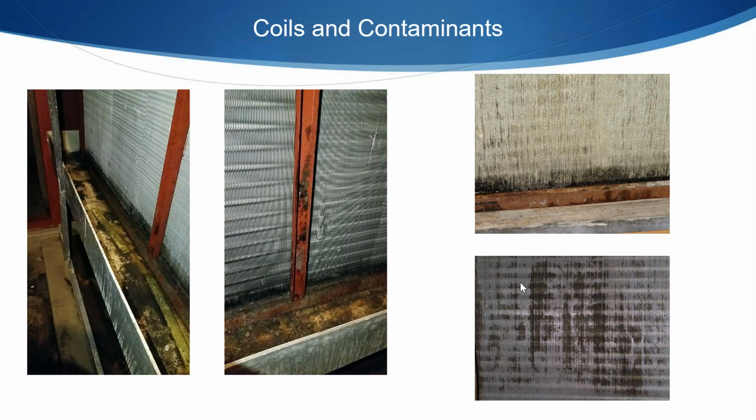And of course, the buildup of mold, number one, is an IAQ issue. It's not healthy to have these environments in our buildings. But also, yes, it does block the coil. There are some studies that indicate you can get about a 15% savings on energy. You also get reduced maintenance costs, and the life of your coil can be preserved a little bit. You're not having to use as caustic chemicals or as aggressive cleaning procedures.